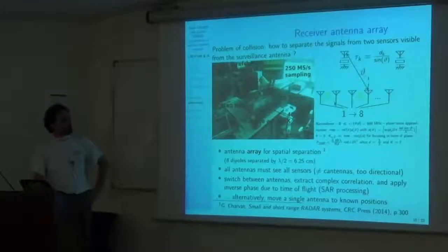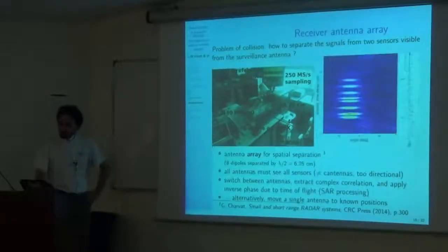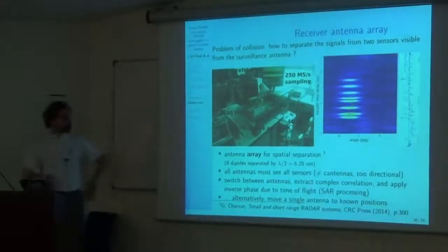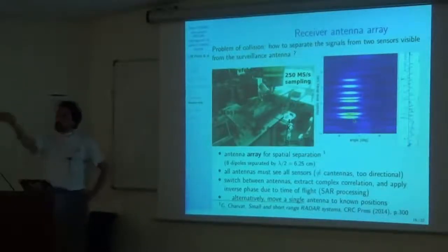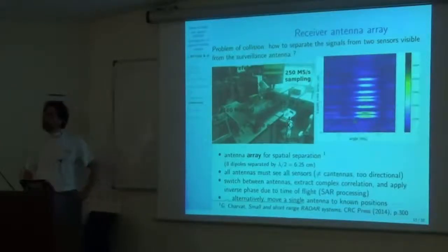Again, we've seen the theory earlier, so I don't have to go back over the details. I have a uniformly placed linear array, so you just apply the same weighting function that we saw earlier. With this array of sensors, you can find the sensor response: 1, 2, 3, 4, 5, 6, 7, and 8 echoes of my sensor. If you remember, this is the time characterization. And I can say, here my sensor is located to the left. If I move the sensor to the right, well, here you are, the sensor has moved to the right. So you have a direction of arrival information.